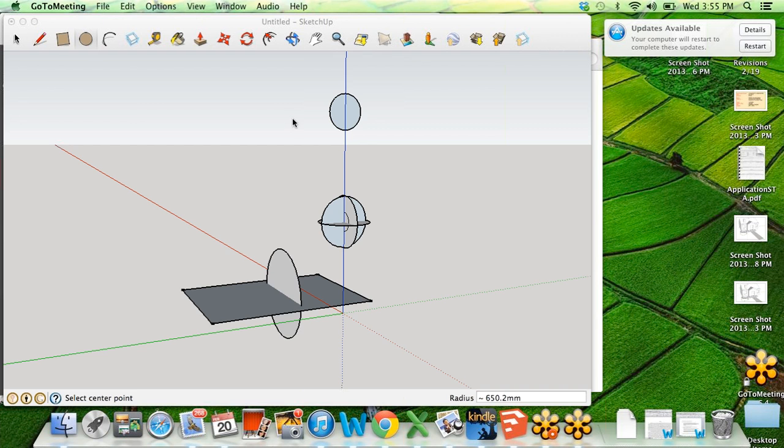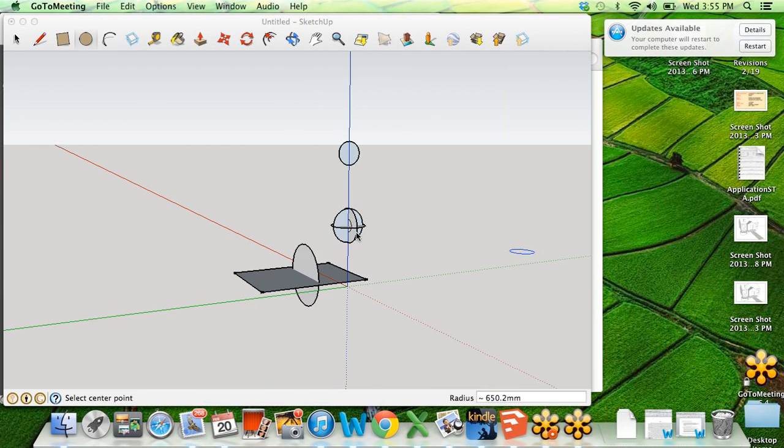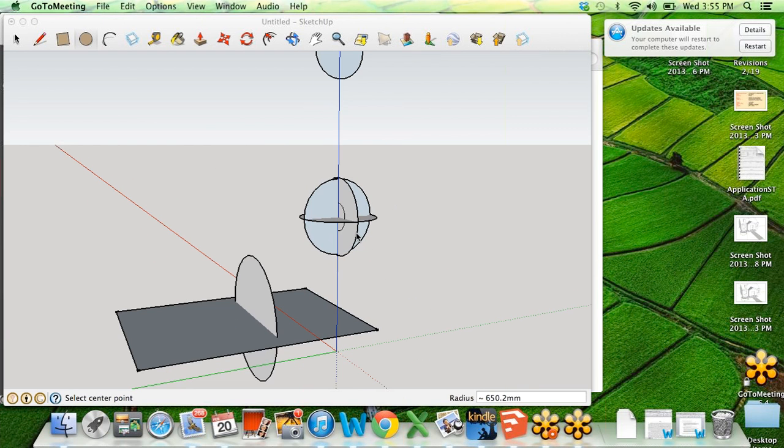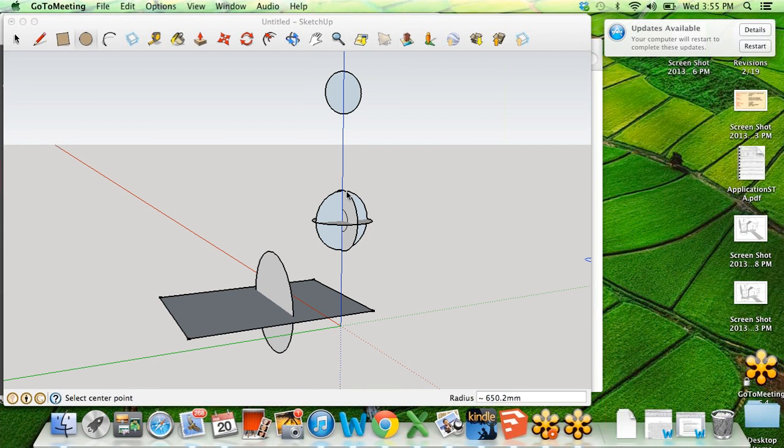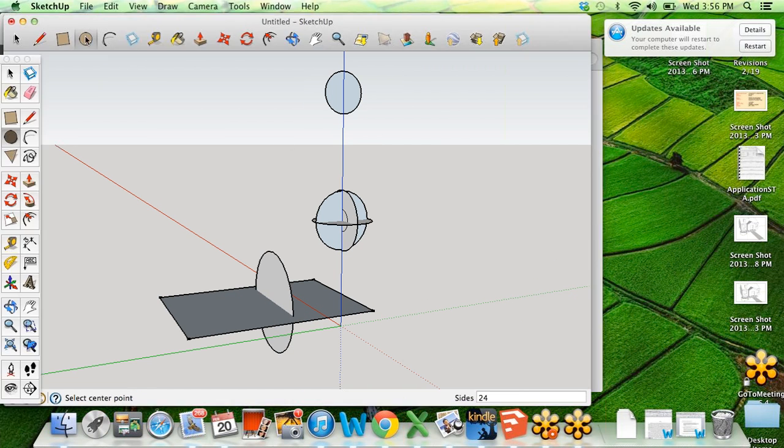How do you get it on the z-axis? That just depends on how you're oriented. Make sure that you have enough space, and you have to kind of mess around with SketchUp. So if I'm down here, it's only going to want me to be on just the XY axis, right? Because I'm down here kind of on what it's calling the flat space.